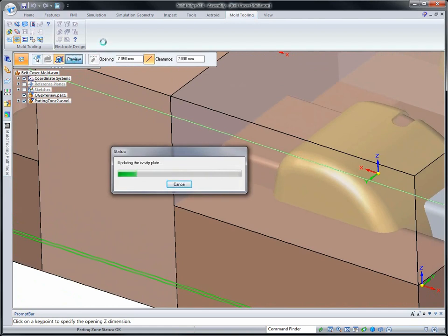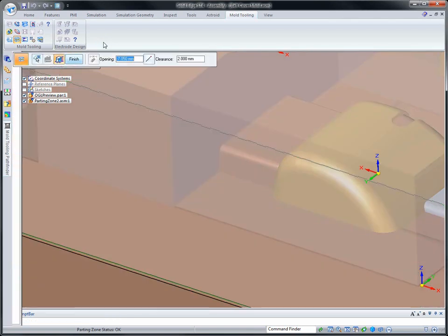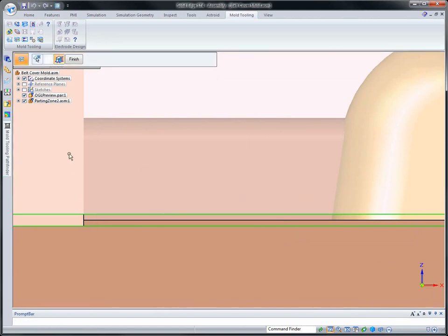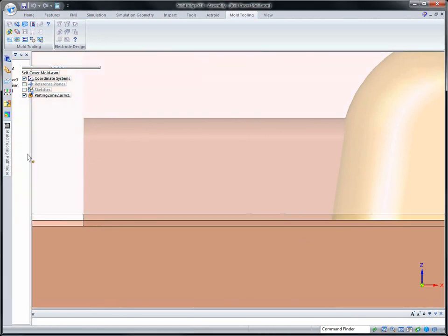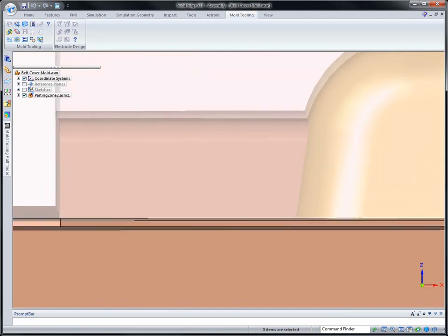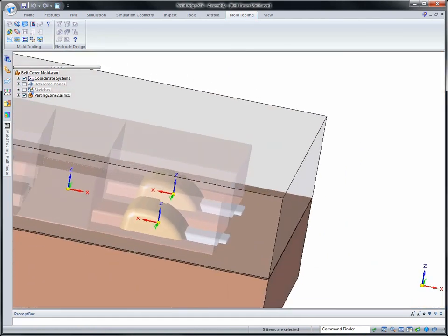And as I said, I used 77 millimeters before to define the height, and that's because of the mold base that we're going to pick. And as I said, I built pinch into this mold, so there's actually going to be a space between the core cavity plates, and you can see now the parting surface, or the parting line, is in between that. So I have a millimeter sticking out of each side of the mold.